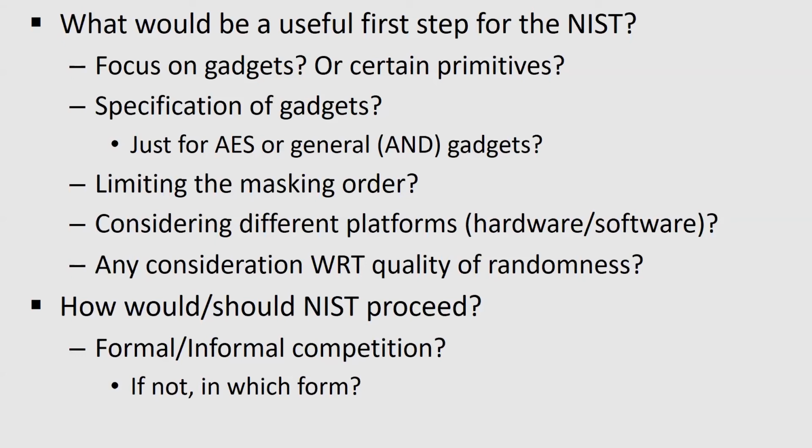So maybe to give my 2 cents on this question. I think that today we know well how to reach probing security for a lot of algorithms with a lot of different gadgets that we know well how to compose, and we can achieve it to arbitrary orders. So I think it makes sense in practice to consider probing security against a type of attacks which are not the strongest attack possible, right? You might consider an adversary which is not so powerful, that cannot have access to a copy device, that cannot profile the leakage, and that will maybe try some more elementary attacks like standard DPA or higher order DPA. And against this kind of adversary, probing security is relevant.